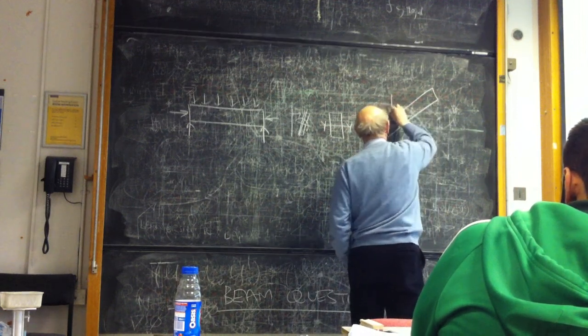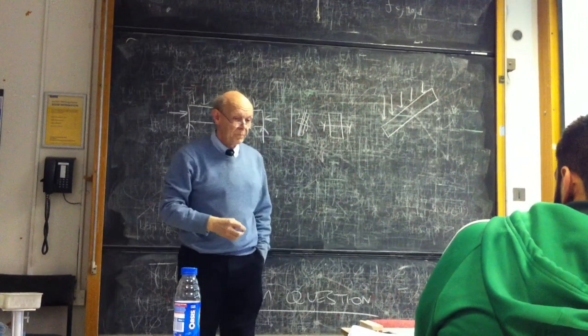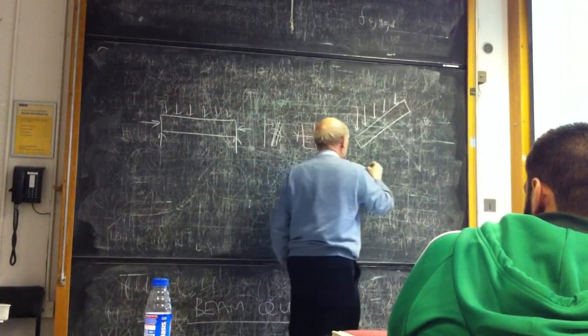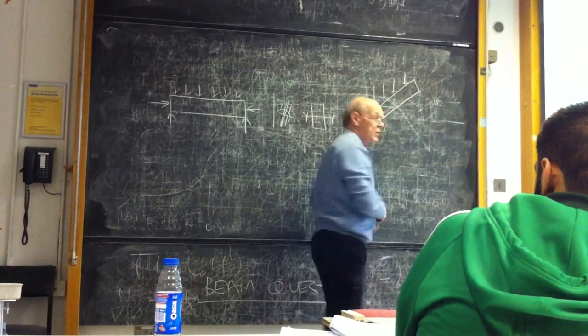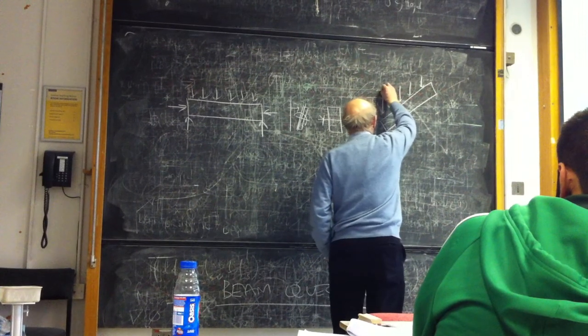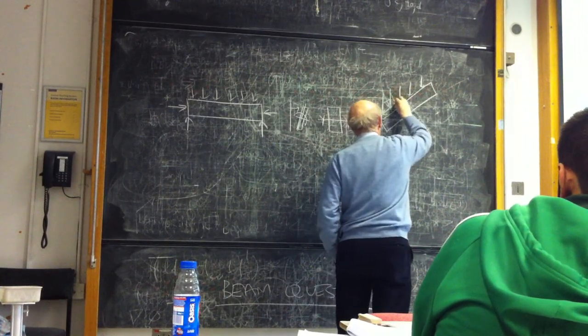where you have loads on the roof, and these loads are going to generate two things. We can look at them like this, which is probably the easiest way to look at it. Each load we could look at as being a load at right angles to the beam and a load down the slope.